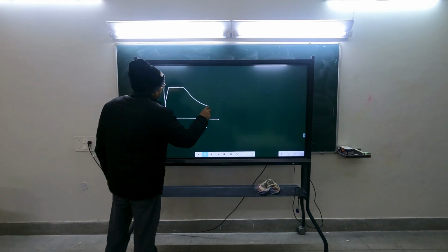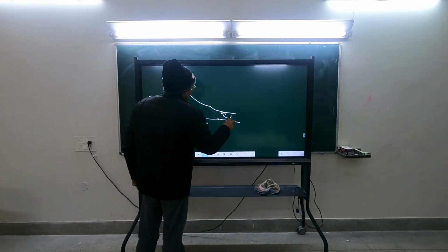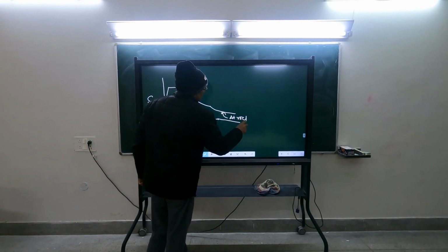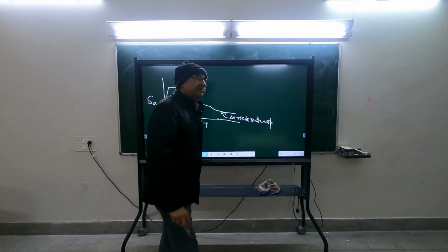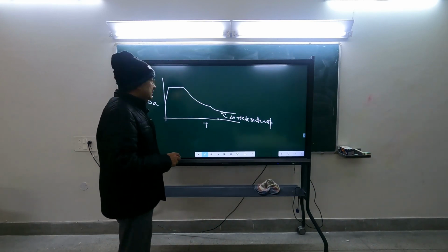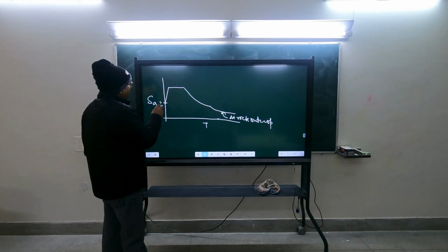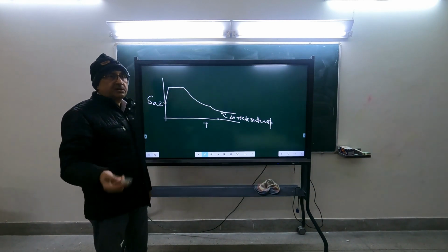So let us say this is the response spectrum at rock. We call it rock outcrop, where rock is at the surface. If you measure that, then let us say this is the response spectrum. Some value of Z it will have, and then you can plot the shape. That shape is given in all the codes.